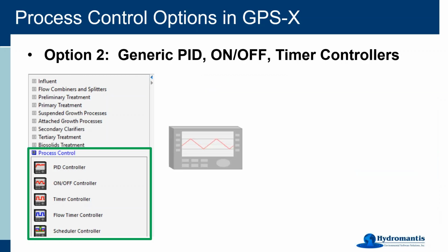All right, so that's a PID controller. Now, the other one here that I use a fair bit too is what we call an on-off controller, but it's probably more accurate to say that it's a high-low controller because you can also do things other than completely off. So the idea behind it, of course, is that you set a high and low band, and then your control variable will be controlled inside that group. So you have a value that's going to go up, and then when it hits this upper bound, that's when the controller activates and does something, and then that's going to hopefully cause it to stay inside this band and then move around. And you want to be able to control it, not specifically to a set point, but just within a band.